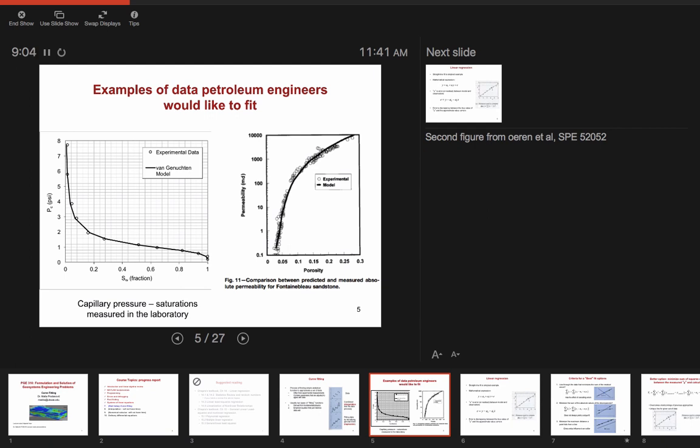The difference in the pressure between those two fluids is called capillary pressure because their chemical composition is different, molecules are different. There is a surface that forms between the two fluids. They're immiscible. Water and oil hydrocarbons are immiscible. And that surface can withstand certain pressure difference, and it curves in response to it. The smaller the pathways that I go through, the larger this curvature is. Right? I bend more over shorter distance. And that makes it harder to push fluids in.